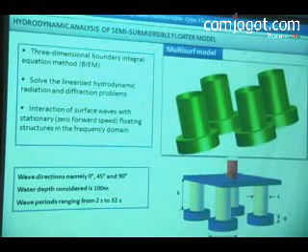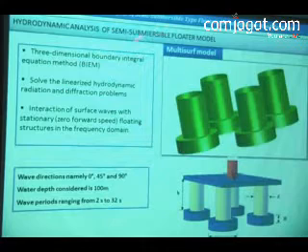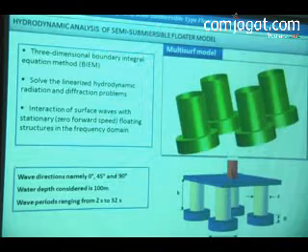The student did the modeling using Multisurf for the semi-submersibles, and the hydrodynamic analysis was carried out in WAMIT. One important thing to note is that WAMIT is a potential flow analysis, and because of the diameter of the columns, it produces large responses in the horizontal direction. So we have to introduce artificial damping to bring down the RAOs.